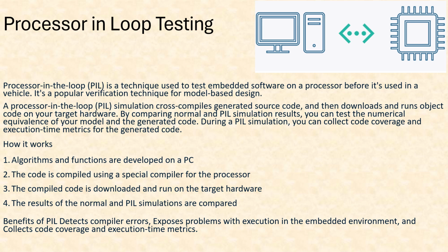It doesn't matter actually whether it is developed manually in C++ or model-based. The model can be developed in Simulink or TargetLink, depending upon the model-based tools, which I already covered. The resulting C++ code must be compiled with a special target compiler for the processor, which is later used in the ECU in the vehicle.